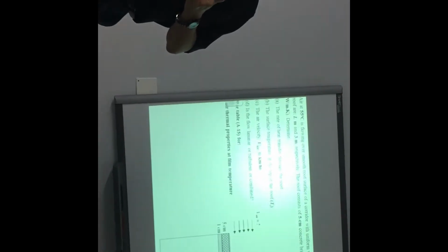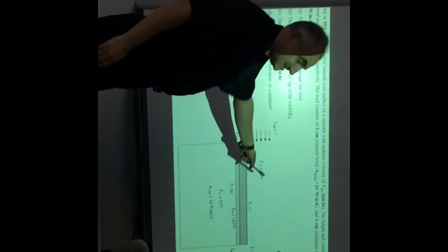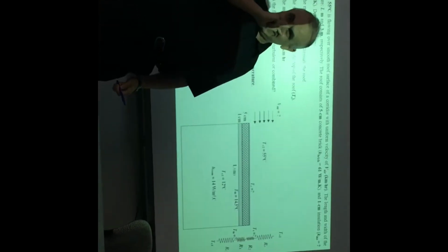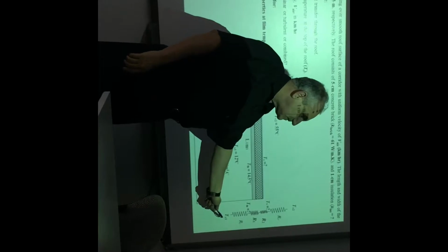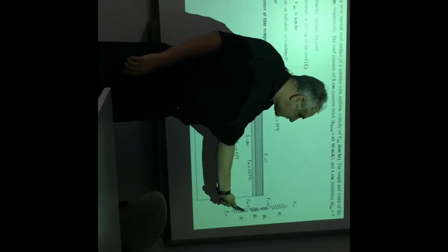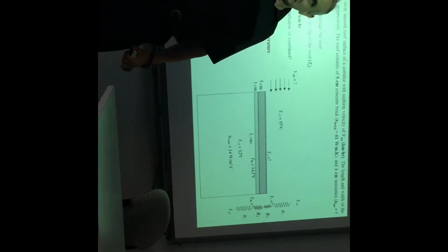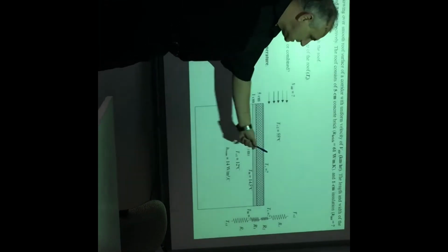Remember in chapter 7, we had the velocity, we calculated the Reynolds number, and then we calculated the Nusselt number. Here you go back, calculate the Nusselt number from h outside. So first you have to find h outside from the resistance. After you determine TS, you can apply Q equal T fluid 2 minus T fluid 1, or T fluid 2 minus TS, or T fluid 2 minus T infinity, whatever. All the temperatures are now known. Correct? Delta T over the total resistance. Then find the resistance. This is outside.